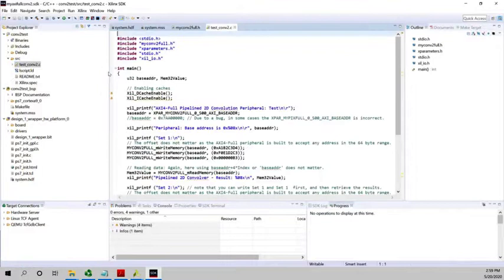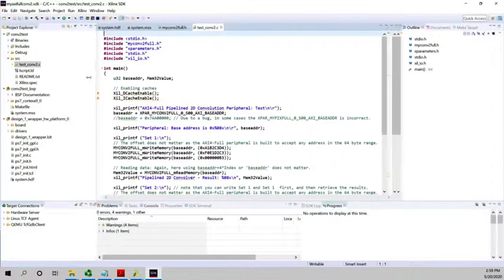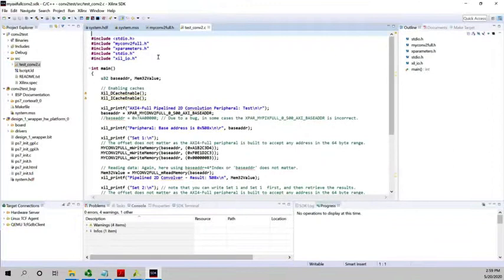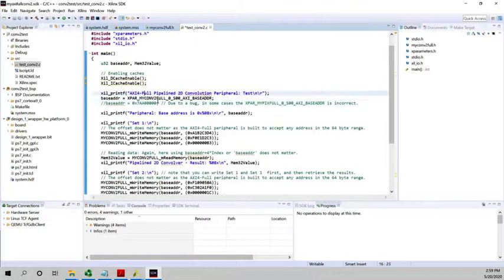And like I mentioned before, if you have your particular peripheral, you are welcome to use this file as a template, right? And you might need to modify it there. Instead of my COM2-Full, say my example, that will be a different name. Here, the base address actually is provided as a parameter into your circuit. So here the main difference will be that it will have to be something like this, right? My example.